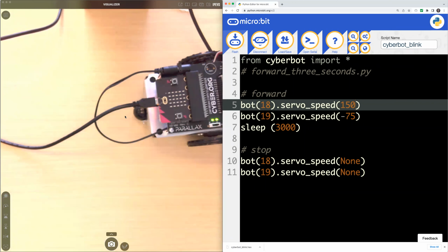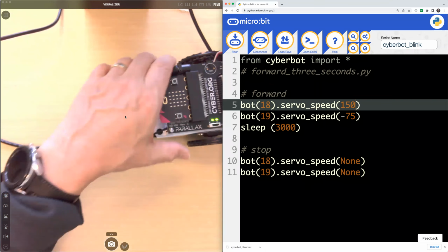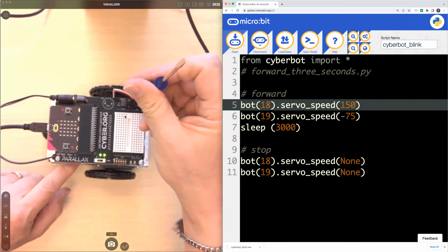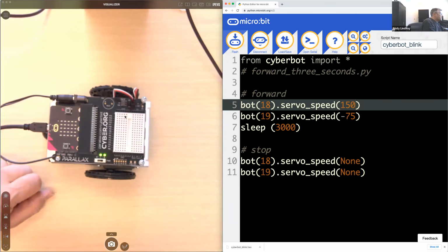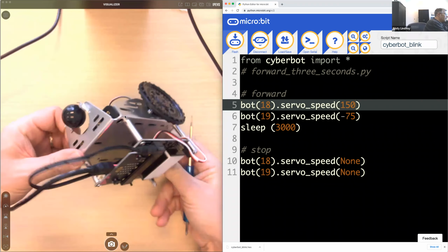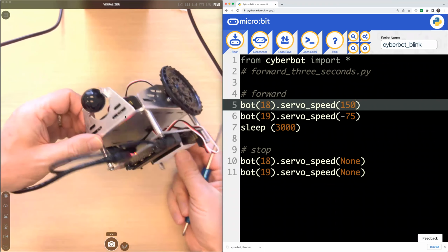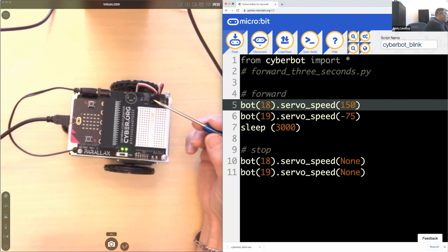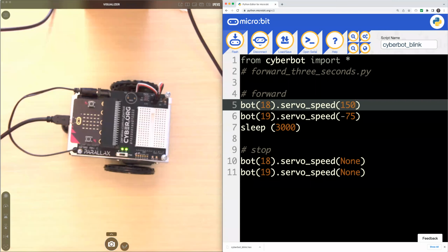I'm just going to mention that the front of the robot should actually be the breadboard near the flat front of the chassis. So that's right here. This is called the tail wheel. Every once in a while, someone will put the board on the chassis such that the breadboard is over the tail wheel. I call that tractor style, and it makes it look a little bit like a tractor. And if they happen to have also swapped the servo ports, it actually all works properly.